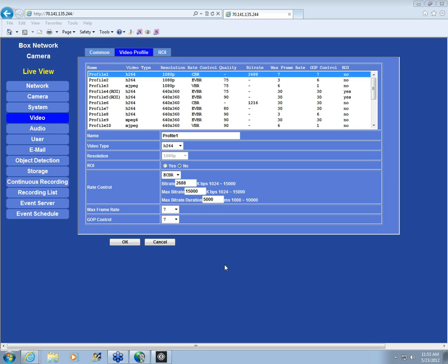So our enhanced CBR is like constant bit rate, but with a little bit of variable bit rate in there too. Then you set the bit rate duration for it, especially at nighttime when the gain is increased to create a better image, the VBR bit rate will go out of control. It'll spike up to whatever level to maintain that quality level. Unlike CBR, eCBR will stream at a constant bit rate, but it will spike up to accommodate any scene changes at a set duration.